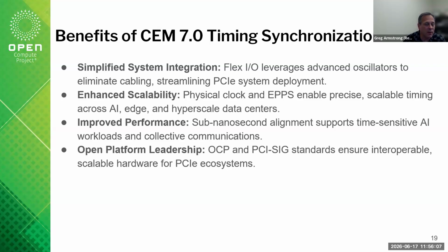And it's also people that are involved in other standard bodies like the P3335 for the time card, right? They're talking about how do we distribute clocks around. Is it over the PCI bus? Is it using PTM? Well, here's now another means of doing that, using the 10 megahertz with the embedded pulse per second.